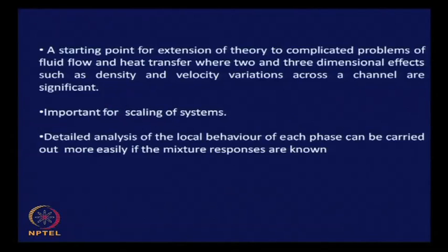Due to its large amount of application coupled with its simplicity, the drift flux model is going to be very useful, and we find that for most of the analysis of multi-phase systems, a starting point is the drift flux model. It is not the homogeneous flow model. Definitely, if we go for the 2 fluid model, where we consider the 2 fluids separately, we will be doing this after completing the drift flux model.